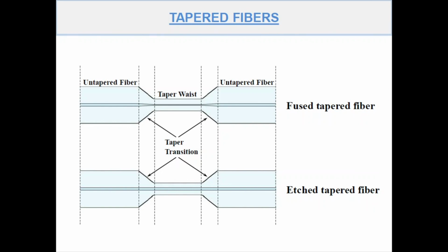The first method is the thermal stretching of the fiber, as a result of which the diameters of both the cladding and the core of the fiber are reduced. The second method involves chemical thinning of the cladding. This approach preserves the geometry of the core, is easier, and does not require special expensive equipment. However, hydrofluoric acid, which is normally used for such purpose, is harmful to health.